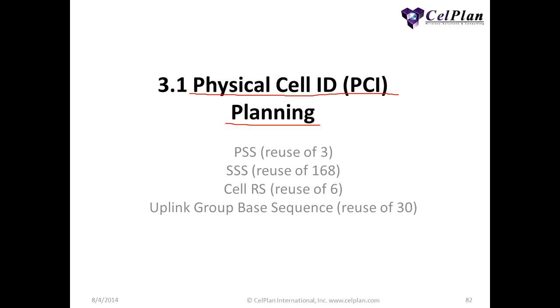Well, to be sincere, in my opinion, the only reason is that LTE had to be different from WiMAX. I think this was a bad decision from 3GPP. The argument was that it will help in terms of PAPR, peak to average power ratio, because OFDM tends to build in some places a large peak, and this requires large power amplifiers and so on.